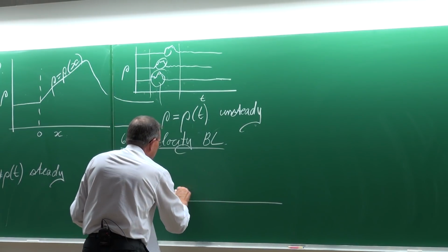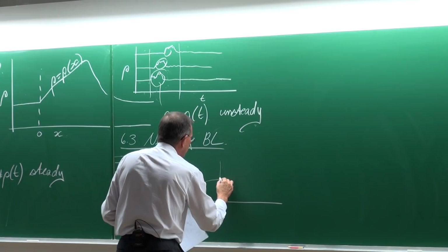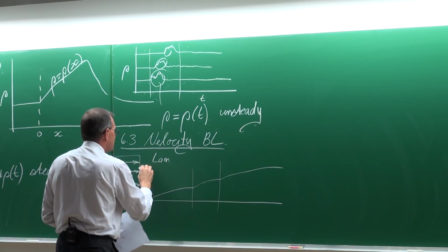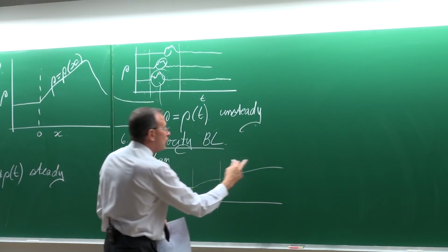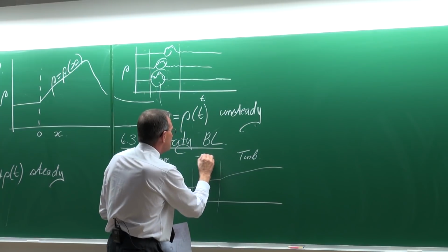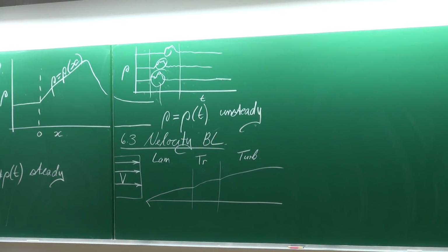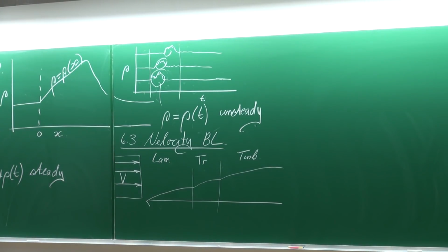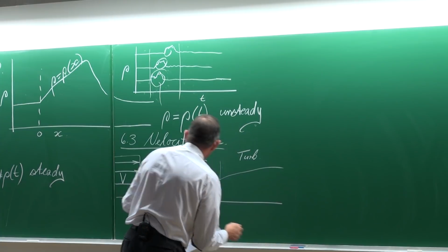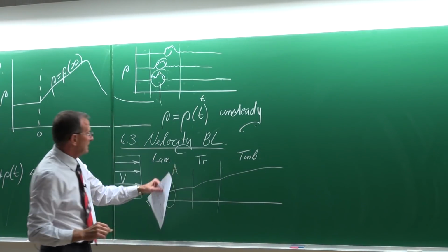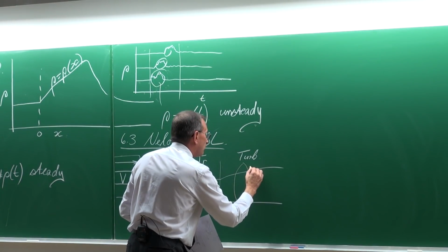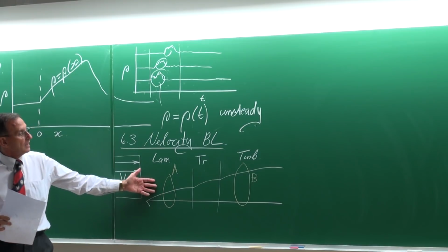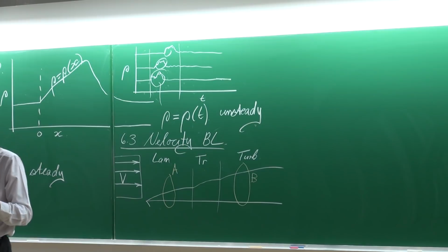And then what is going to happen is three different boundary layers are going to form. Firstly, this first part, which is considered as a laminar flow, this part, which is considered as turbulent flow, and this part is considered as the transitional flow regime. How the flow changes from laminar to turbulent, that is known as the transitional flow regime. And what we're going to do now is look at the velocity distribution typically here at A, and compare it to the velocity distribution at B. Therefore, the velocity distribution during laminar flow in comparison with the velocity distribution during turbulent flow.